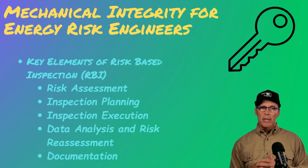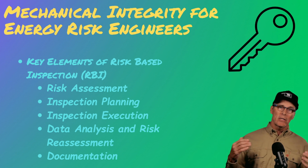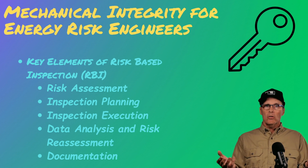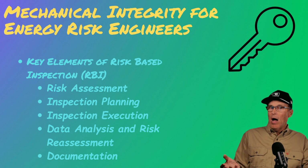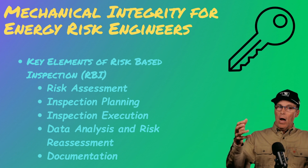All right, what is in the risk-based inspection? We're going to have to do an assessment of the risk. And when we do that, remember, risk is the likelihood times the consequence. So we're going to go out and look for things that have either a high likelihood or a high consequence, and that's what we're going to assess as higher risk.